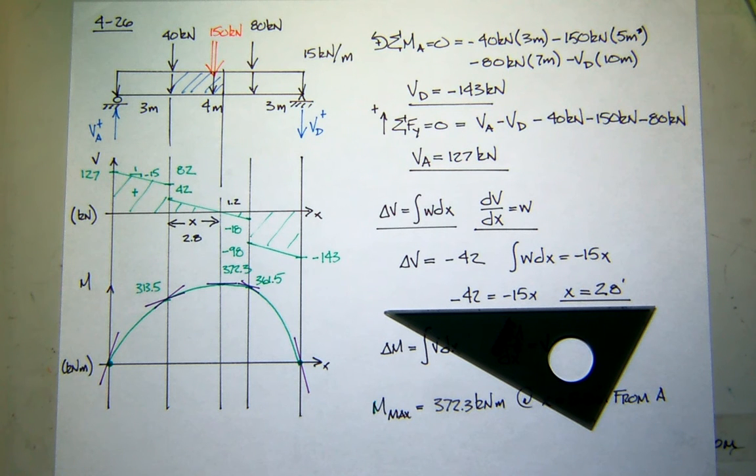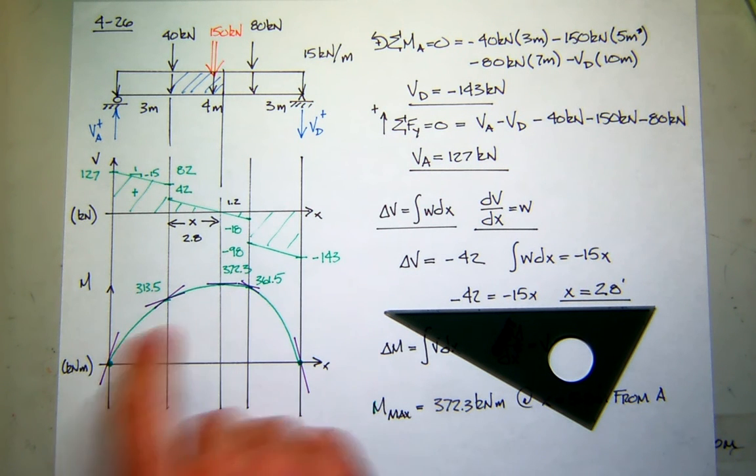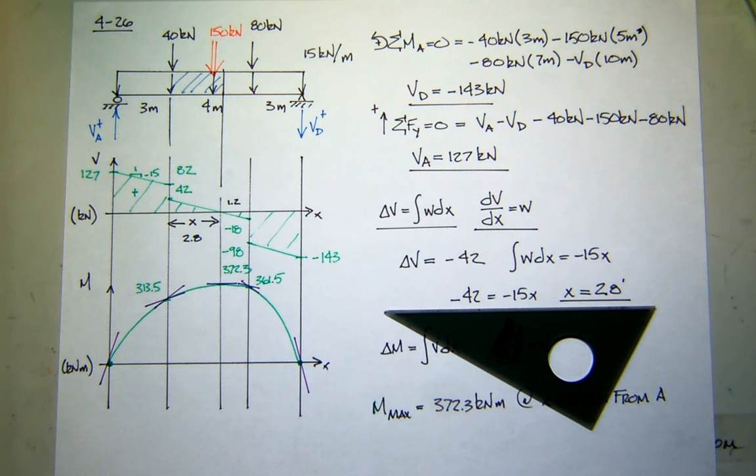Well, in shear, all I care about is the maximum shear. Now, if I ask you what's the maximum positive shear, then that's a different answer from what's the maximum negative shear. But really, in structural engineering, we don't really care. We just want the maximum shear. But moment needs to be reported as positive or negative. Yes. Because there could be a possibility where you'd have some negative moment, positive moment. If it was a concrete beam, you'd care about both of them.